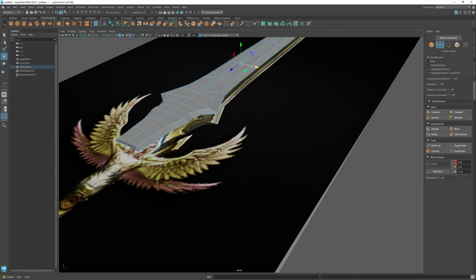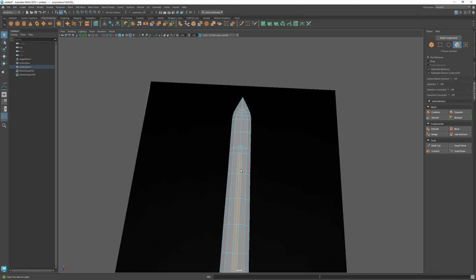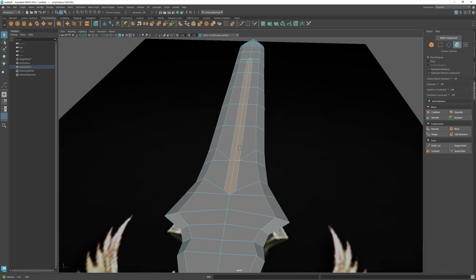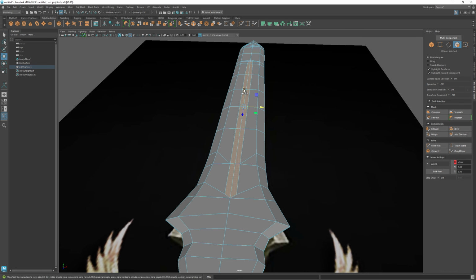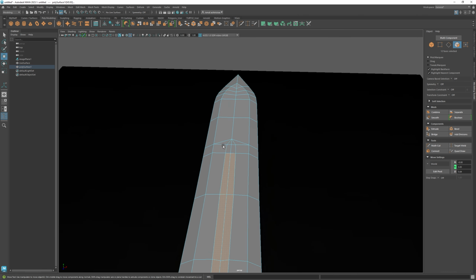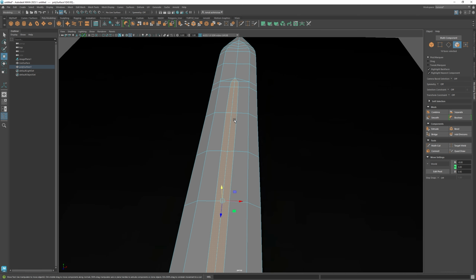Okay, next thing is that we want to do the extrusion of this. Maybe we can make this texture a light effect, emissive, or something like that. Okay, so extrude, I can press shift and move this lower, or I can use tab.